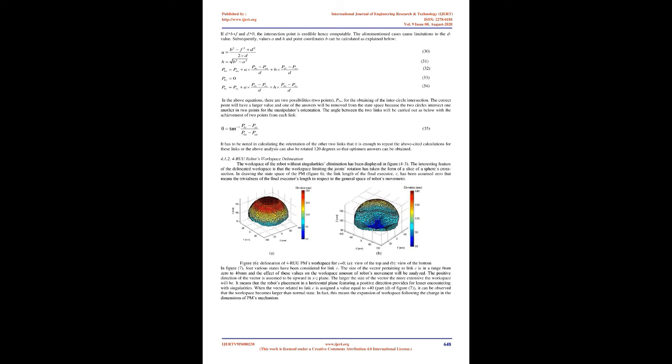In fact, the inverse kinematic method can be used for the determination of the points the achievement of which is accessible to the mechanism designed for the robot. The shape and size of the workspace can be drawn in a process with the determination of the individual workspace points. The first step in the calculation of inverse kinematic is mapping the final executor's position on xz plane. In this case, the length f is the distance between pb to pa mapped on plane y equals 0 and it can be calculated as explained underneath.